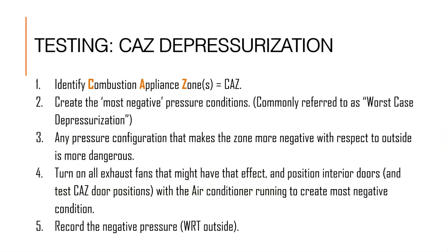CAZ testing, or combustion appliance zone depressurization, is a critical part of both the building performance and weatherization industries. We identify the zones of the home that have combustion appliances with the purpose of testing those zones to see how much negative pressure can be created. When you have measured and compared your way into what you know is the worst case depressurization, then we fire the combustion appliances to confirm that all of the combustion gases are still able to vent out and are not spilling or being backdrafted into the home.